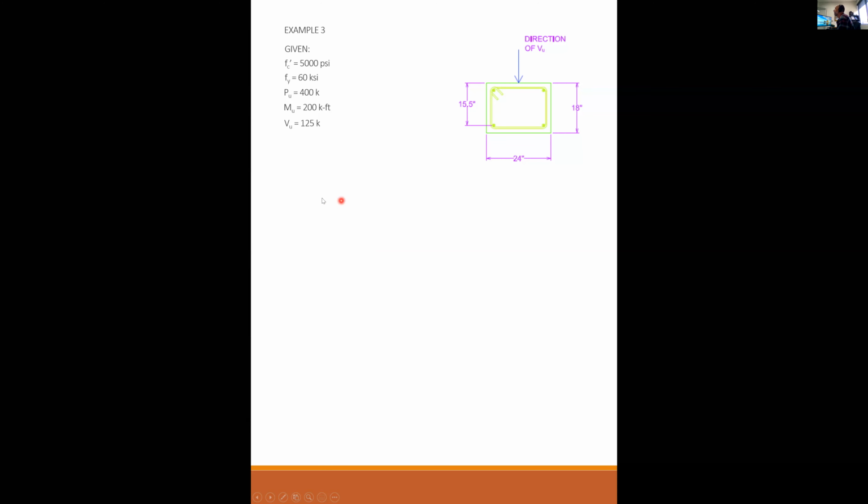But if I have a shear load of 125 kips on this thing, if I use number 4 grade 60 ties, what spacing do I need to put them at? So this is one number 4 grade 60 tie. As I explained before, this is not California. You couldn't build this column in California. But given that this is anywhere else in the world other than California, based on this information, what's the required spacing for these number 4 ties? If you use the simplified equation 22.5.6.1, or if you use table 22.5.6.1.